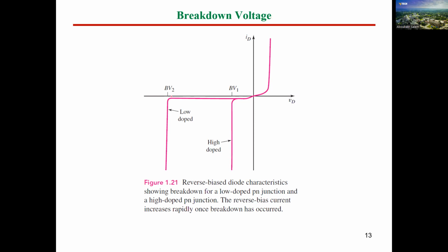Here we have two different values for two different diodes. And here, as you can see, guys, this is in case of highly doped and this is in case of low doped material. So it depends on the doping of the material in our diode. So this is now the complete characteristic. You don't need to draw two characteristics, one characteristic is sufficient. So let me draw the characteristic like that. This is going to be the plus or forward biasing, and in the reverse biasing, I'm going to draw it like that. And I have to define the terms. So this is V, this is I, here forward, here reverse, and I should mention that this is V breakdown.